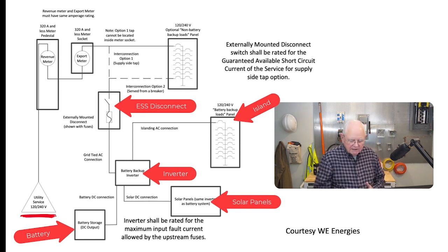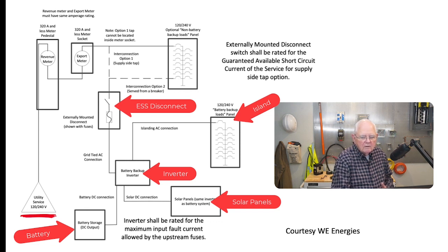And with that disconnect closed, that is just what we're doing with this interactive inverter. We would be supplying this panelboard in parallel with the utility.